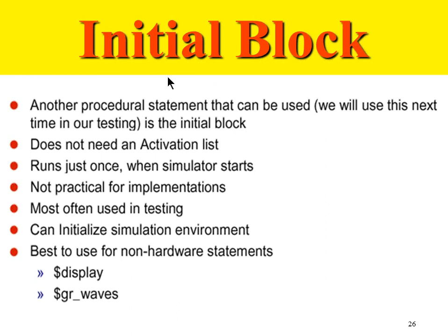Do you understand this concept of the initial block and where it could be used? Yes. Typically, if you have any memories, any memory has to be initialized to some value, it could be 0 or 1, every bit. That initialization of the memory will always go in the initial block.